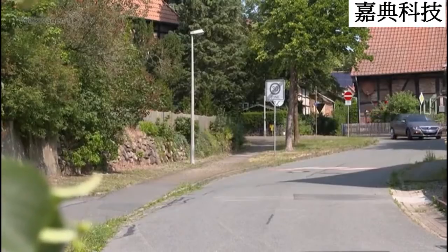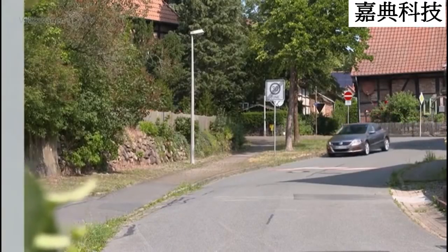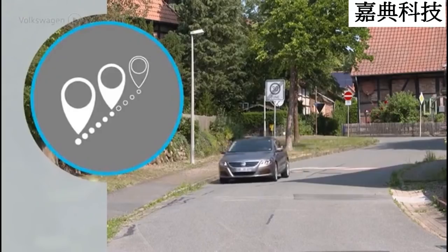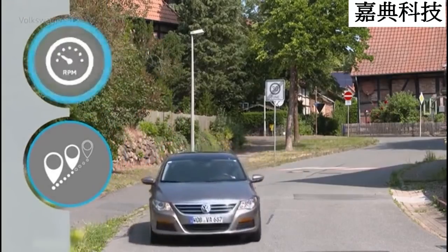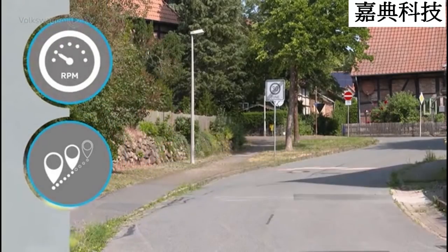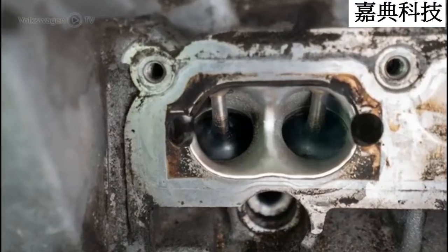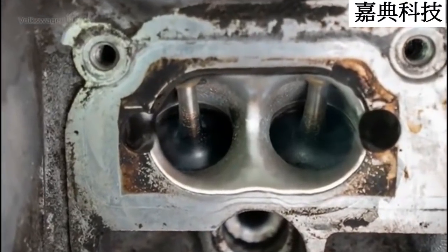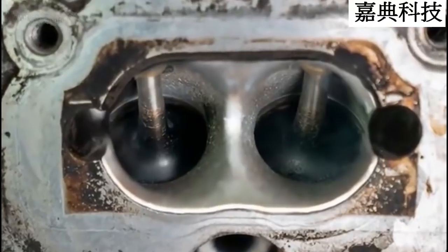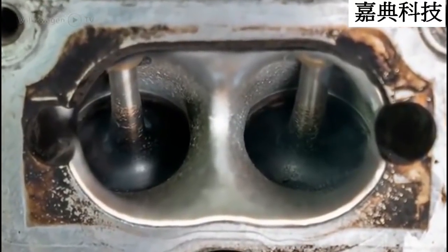Primary cause might be found in the customer's driving profile if they mainly drive for short distances and at low speed. In engines with manifold injection, the fuel washes around the inlet valves and ducts, cleaning the components.